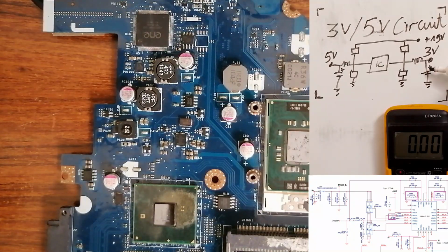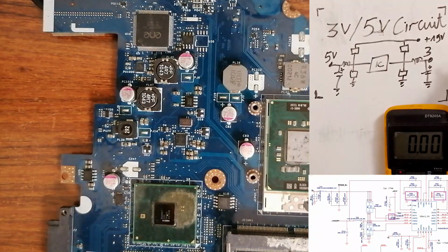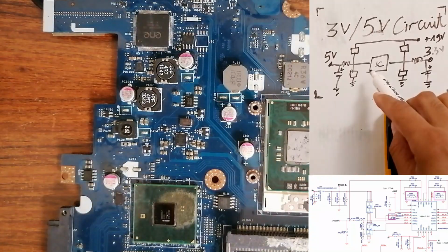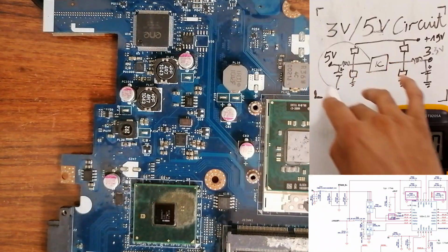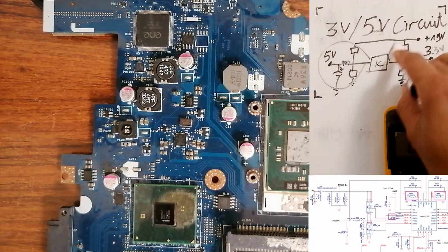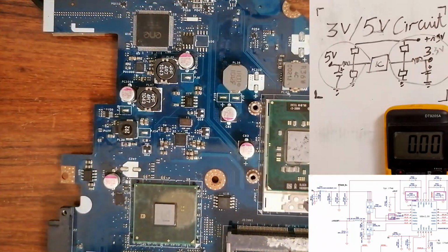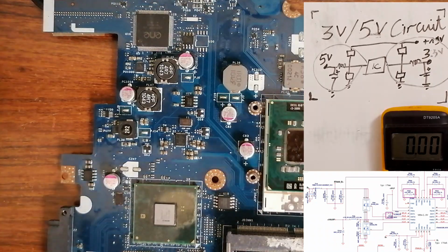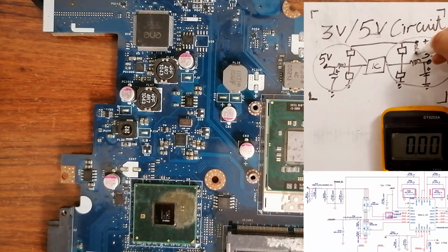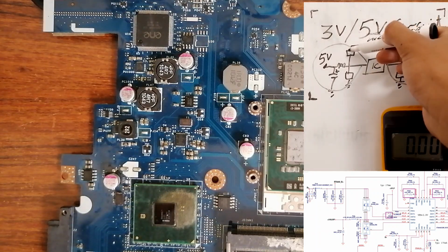The purpose of this capacitor is to filter the voltage and get basically a pure 3.3 volts. Okay, the same for the 5 volt circuit or channel. We call this the first channel, and over here we have the second channel. And as you can see, of course, we have 19 volts. This is B plus. Over here we have B plus. Okay, this B plus will be applied to this channel and also to this channel.